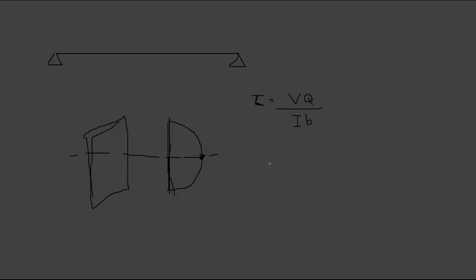So this is the shear force, and this shear stress becomes maximum at the neutral axis. So that means now we know at the support your shear is critical, and now we know along the section what the critical point is, right?